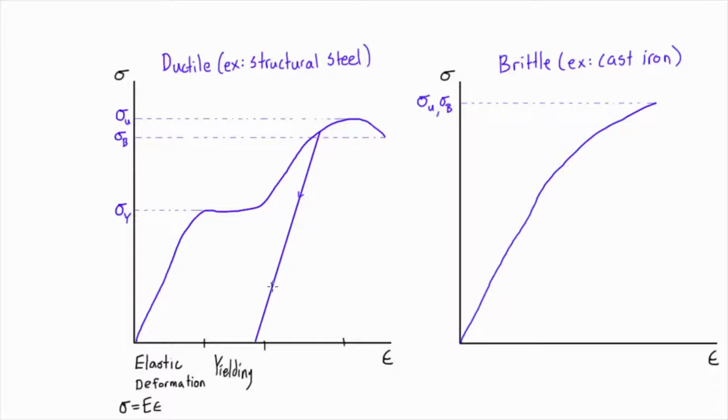and when we unload the applied force on this member, the stress strain diagram falls back down to here, and we're stuck with even more deformation than before. But then when we go to reload this member, we go up this way, and we've created this region that will now act elastically to the point where we come back to this amount of deformation, but we can achieve a much higher internal stress that gets closer to our ultimate stress. So if we push it even further, we get to this last point, the top of our curve here, which is our ultimate stress.